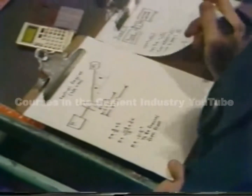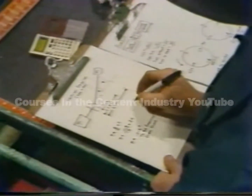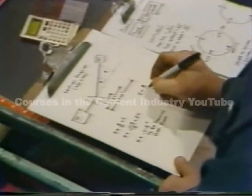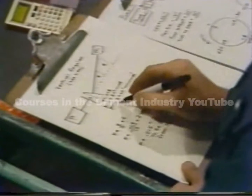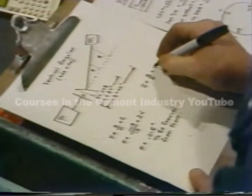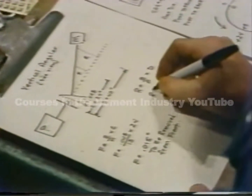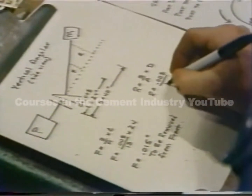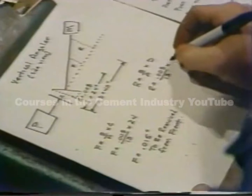The equation for the rear feet is the same. R for rear equals B over A times D. This time the distance to the rear feet, in this alignment, is again 8 thousandths divided by 13 times 40.